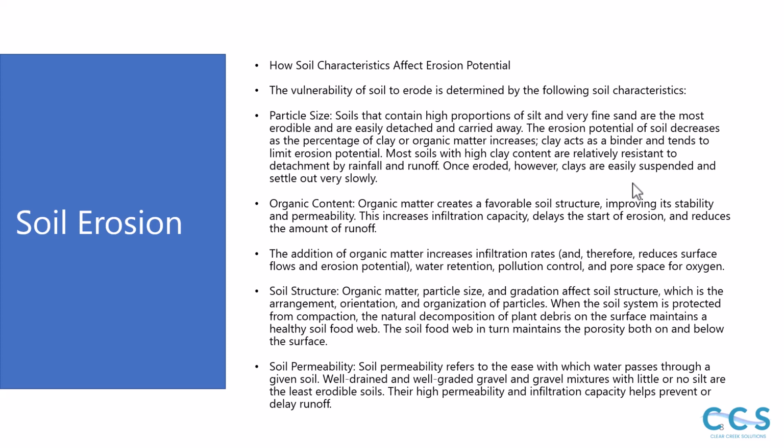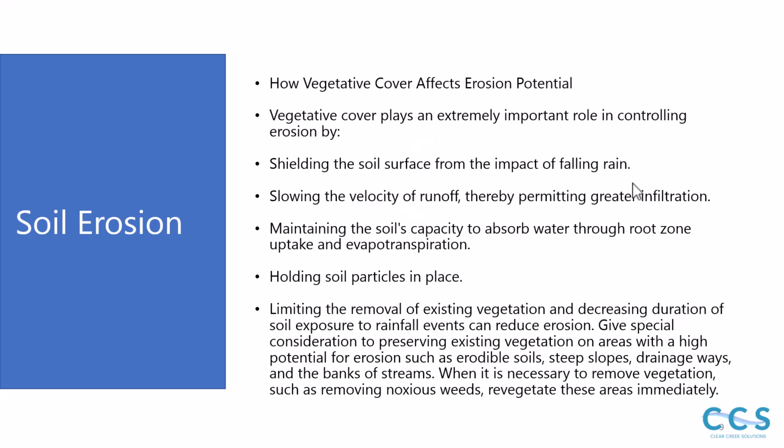Then soil permeability. Soil permeability refers to the ease with which water passes through a given soil. Well-drained and well-graded gravel and gravel mixtures with little or no silt are the least erodible soils. Their high permeability and infiltration capacity help prevent or delay runoff.